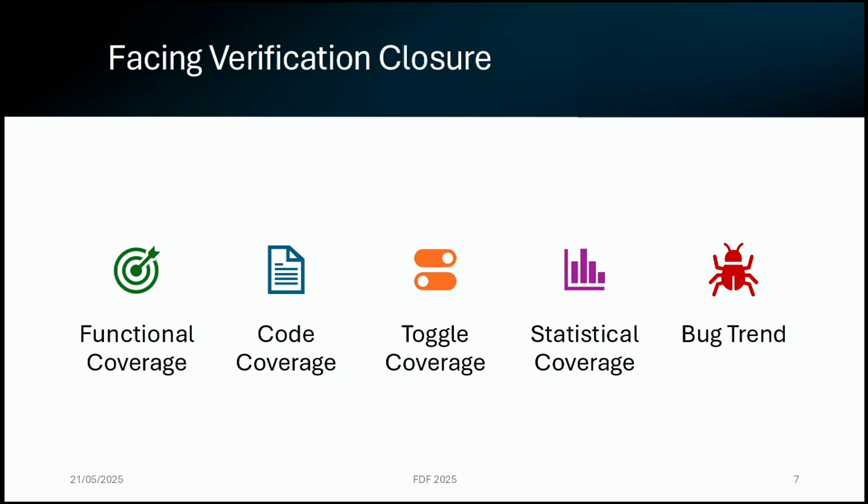But then the problem of functional coverage is that you're writing it, and you're human, so you might forget to write something. So you will never have a complete set of functional coverage. That's why we need more types of coverage. And code coverage is one that is very helpful. Code coverage tells you if you executed all the pieces of code of your design. I'm simplifying this a lot because code coverage is many things. It can be line coverage, expression coverage, branch coverage.